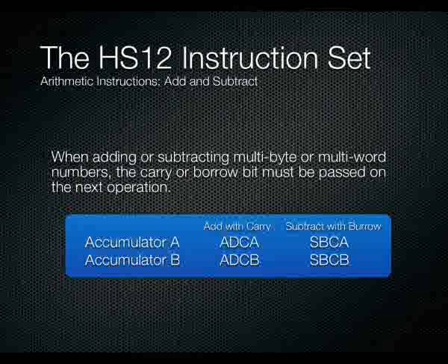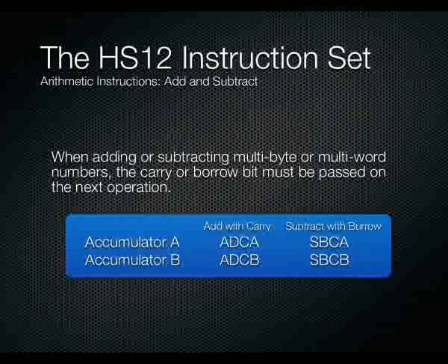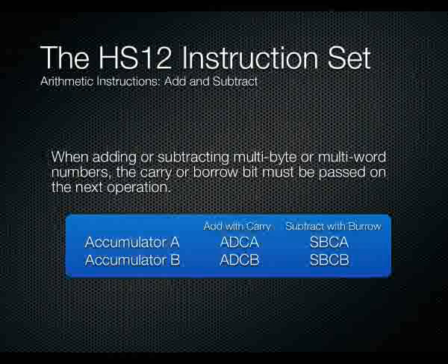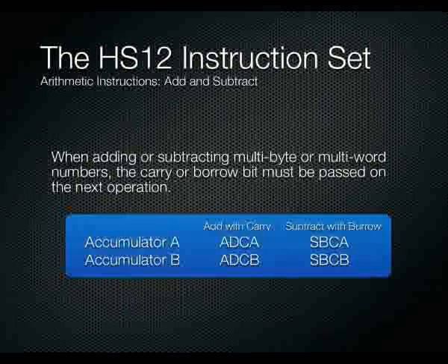And of course, you've got the same thing with subtraction. If you need to, say, subtract the bottom two bytes, and it's actually had to borrow from the most significant bytes, then in fact you can do a subtraction with borrow, and then it will take into account the borrow that you've borrowed from the most significant bytes.